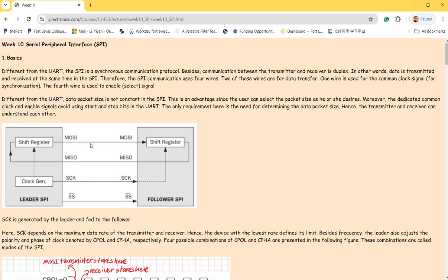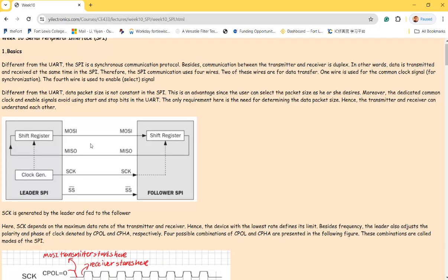So for our senior design this semester, we are trying to design a temperature sensor for hot tubs and transmit the signal through the cable to the data center. Sometimes the conduits and the cables are pretty long, and that's why we don't want to consider SPI, because it's too fast. SPI communication is usually running at 1 megahertz, so 1 megabit per second, which is pretty fast. I2C, 400K. UART, you know that, you can change it, right? UART is usually 9600. It's the slowest. 40-year-old technology.